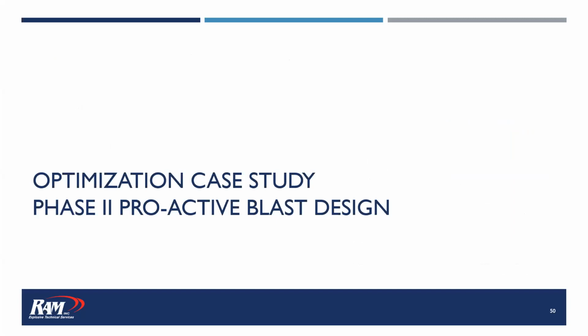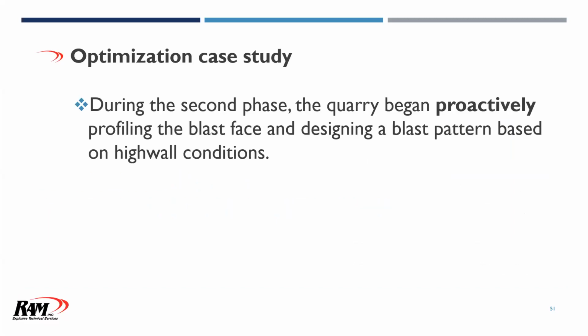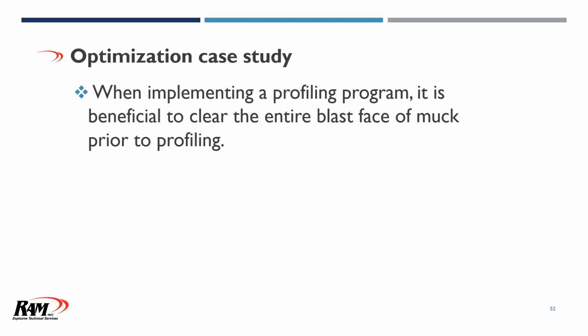Which brings us into the proactive part of this, recognizing these issues. They now saw that they had to go forward with some major changes to get this fixed. So the idea is to go in there proactively, design the blast pattern based on the high wall conditions. And I can tell you that not only there, but the other places we go, this has been the most successful way to approach this and be able to get these shots optimized and gain some good economic value out of it.